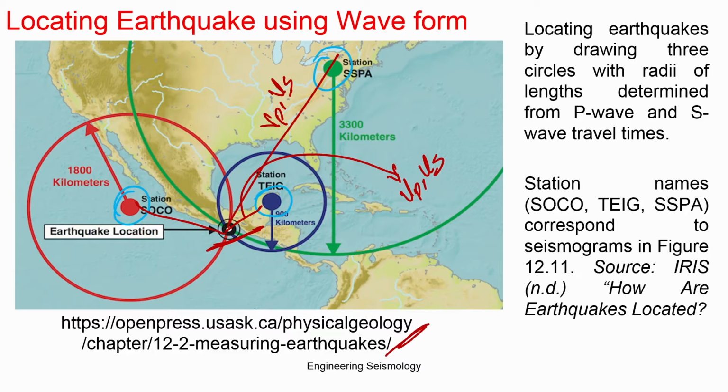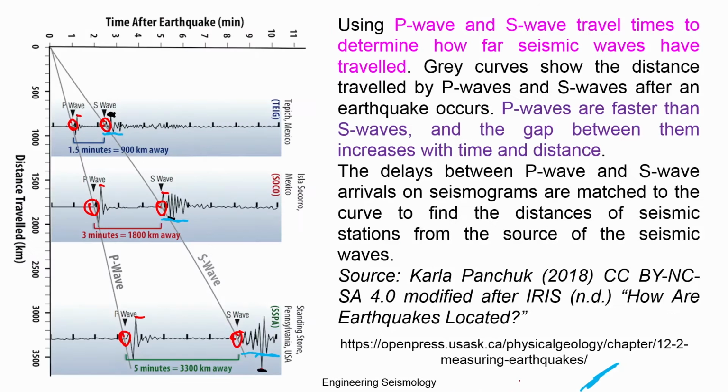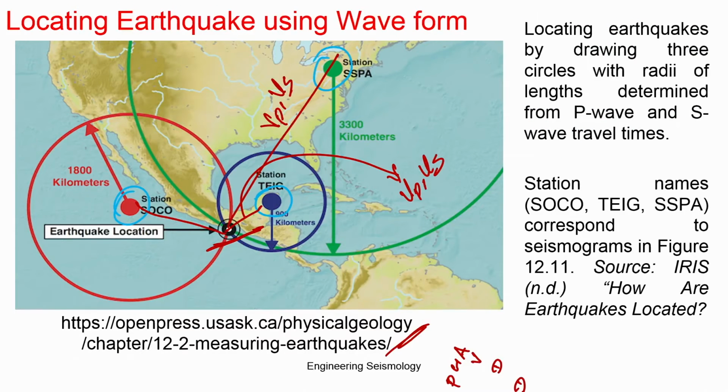Okay. So this is the direct wave where we can expect the PGA, PGV and PGD, and then a duration, which we have seen here. Depending upon the type of duration, your threshold value keeps changing, but this is the data we will predominantly use to arrive at the duration. So these details will help you to infer from the earthquake data what is useful for engineering applications.